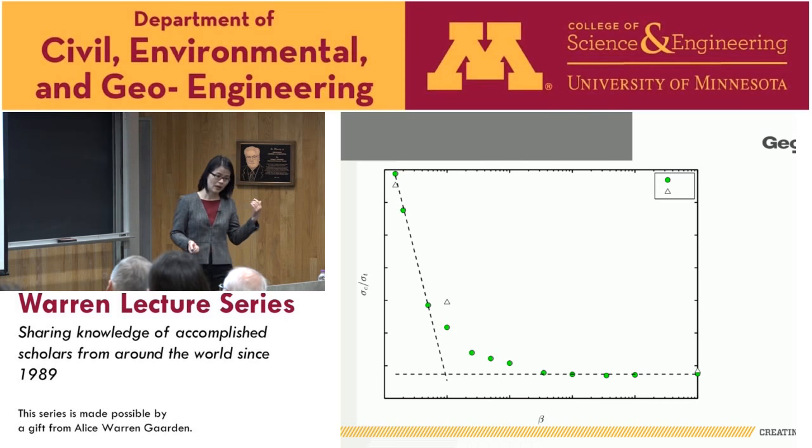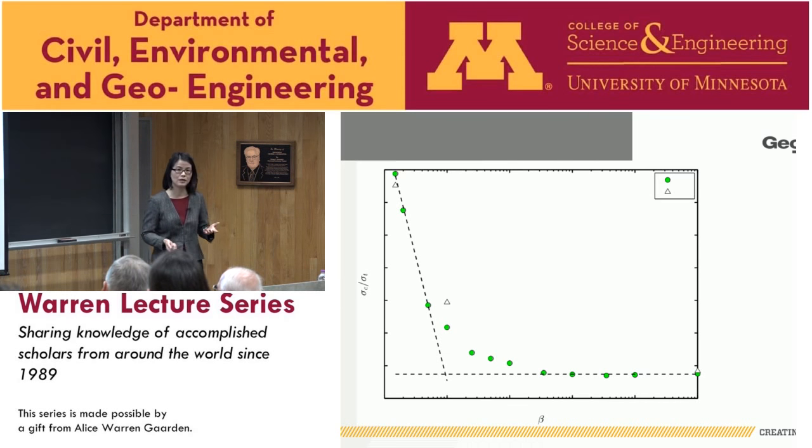And actually, when I go back to the literature, I've seen softening laws being presented in some of the papers regarding contact laws, and nobody really came up with a ratio this high. They were still in that range. So I suspected that even if people put in some numbers, sometimes they were probably just exploring the range over here, and therefore they didn't realize the softening laws are actually working to help them get the high strength ratio.